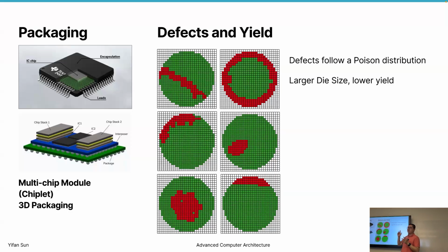This is very likely caused by your mask being slightly, like a few arc seconds, twisted. In the center, it's okay, it's not that bad. But if it's not perfectly aligned on the side, it just has no way to work. And this is probably more like something happened in the center, something happened here.